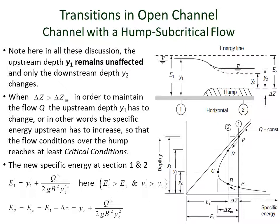At the new upstream flow depth, which is called y1 prime here, the specific energy can be given by the equation E1 prime equals y1 prime plus Q square by 2g B square y1 prime square.